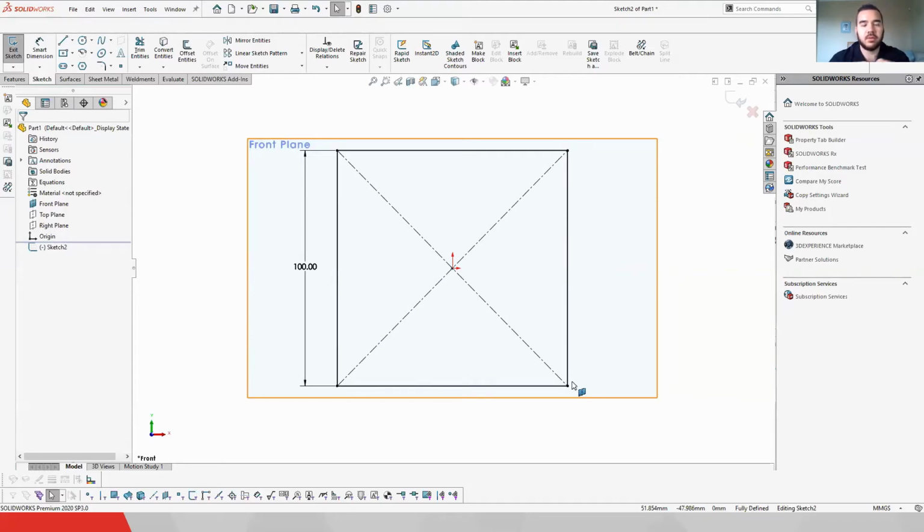The reason for that is if you get into practice and I take my sketch and give it to someone else, and it's not a fully defined sketch, there are ways they can incorrectly go and design that. So always try and get your sketches fully defined. You'll also notice at the bottom of the screen, it'll actually tell you it's a fully defined sketch. Okay. So that was just a basic rectangle.